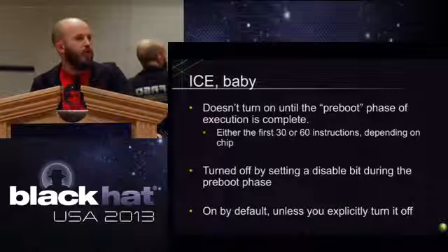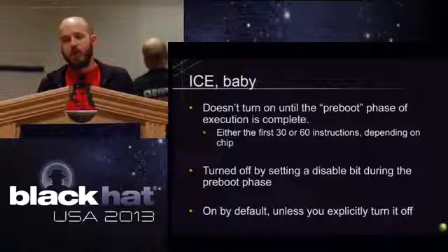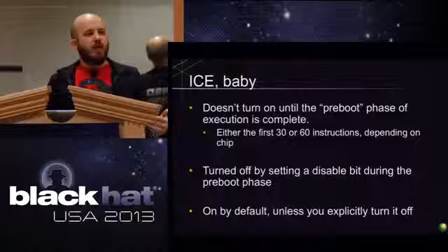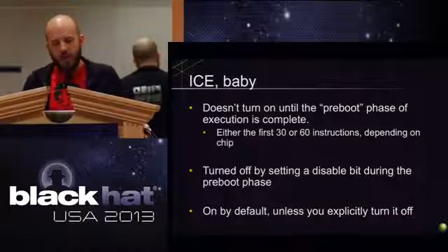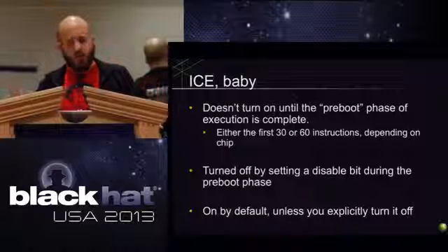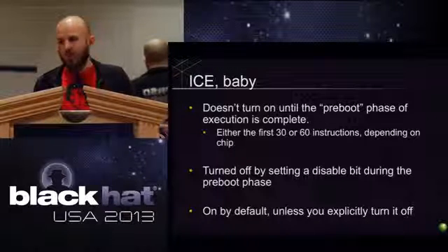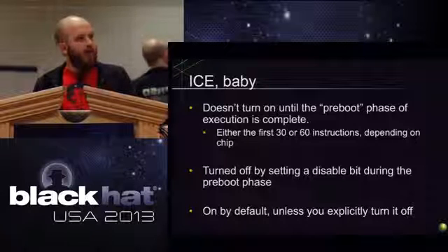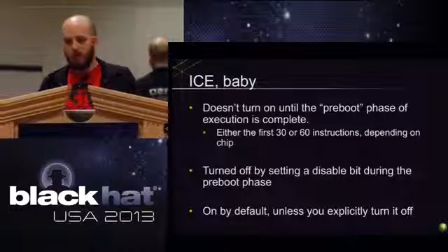It's turned off during that time period, and then at the end of that pre-boot phase, which is either 30 or 60 cycles, it may depend on the documentation version rather than the chip. I think somebody made a mistake, but it doesn't matter. It's so small that it's imperceptible for us for the most part. And then it gets turned on. It's turned on by default every single time you apply power, unless you set a specific bit that says, hey, don't turn me on.